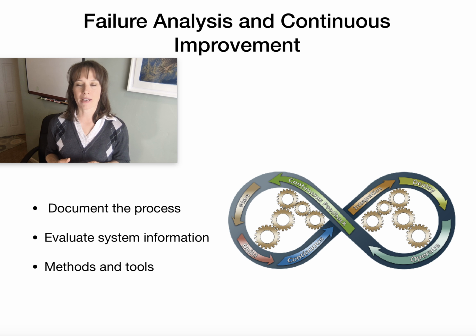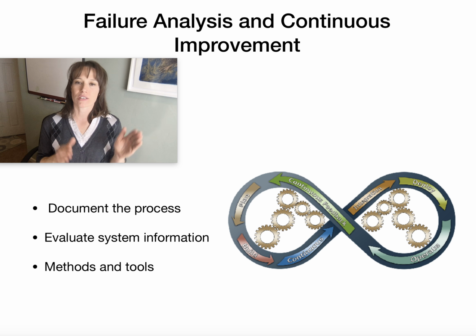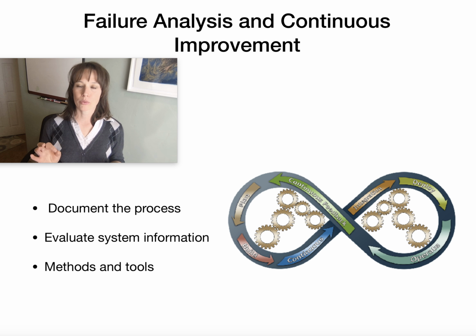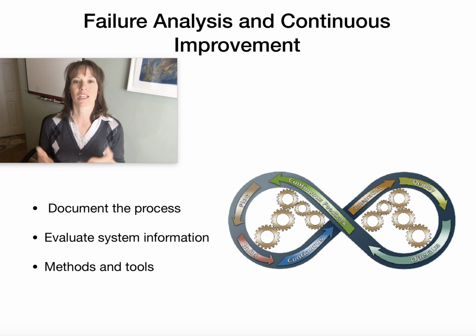do some continuous improvement. Along the way, hopefully you've been documenting, or you have notes, you have your paperwork that you filled out, and also you have documentation if you're working on an automated system that's collecting data such as SCADA. That's been documenting the process continually. It is collecting data, and you will have that readout because you might not remember which things happened in which order. And we talked about the first out. That's a really important clue of which piece of equipment or which alarm went off first. And so then you're going to evaluate your system information that you have pulled together.